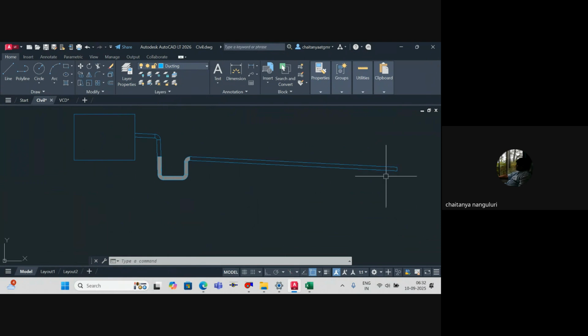But whenever you have stopped the equipment, say probably 1 month or even 1 day or 2 days also, water will be stored in this so that you make sure that small rodents or insects and all cannot swim through this water and it will not enter into your indoor space. So both ways you have protection. One thing is you're making sure the fan is not sucking air from the reverse direction. Second thing is you're making sure pests or insects are not entering into your space. Understood or not?